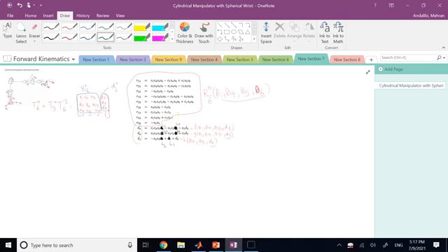Okay, so clearly you see they make sense, and now you see they are quite complicated nonlinear functions. There are lots of sines and cosines, as you can see, that are multiplied together. These are multiplied by sine and cosine of the angle, so the equations are absolutely nonlinear, but the good thing is they give you a unique solution. So when I have theta 1, d2, d3, theta 4, 5, 6 for this robot, and I know L1 and L2 from the geometry, it's just writing this equation once, and then each time is plug and play. So at any joint vector, I can find the location of the end effector and orientation of it, so I can see what I'm doing in the workspace. So I can go from Q space to workspace, and that means forward kinematics, right?